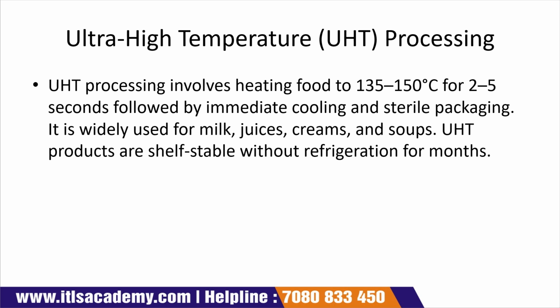Next is ultra high temperature processing. In ultra high temperature processing, we use a high heat for the preservation of the food product, and that heat is very high, around 135 to 150 degrees Celsius, but the time is very short, around 2 to 5 seconds. So you can see that when we have a low temperature, then the time is high, and when we have a high temperature, then the time is less. So this time and temperature combination is very important.